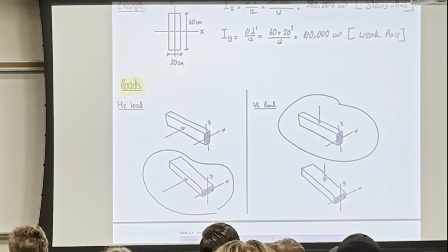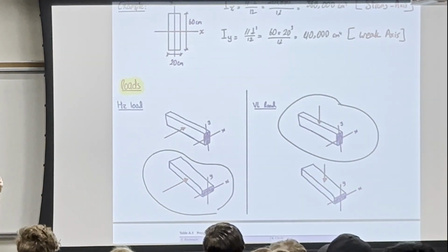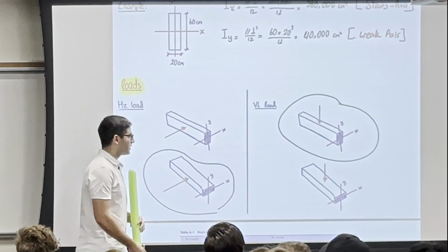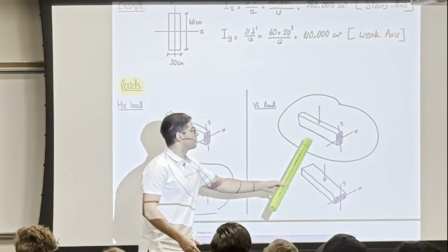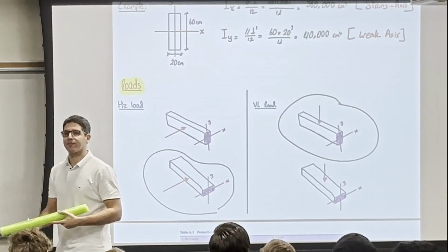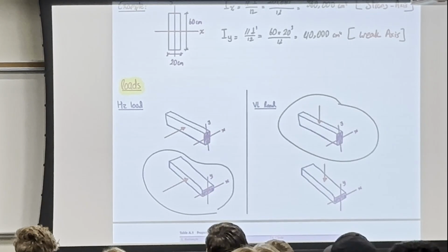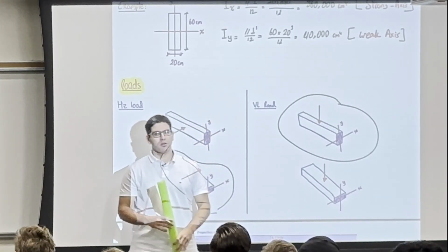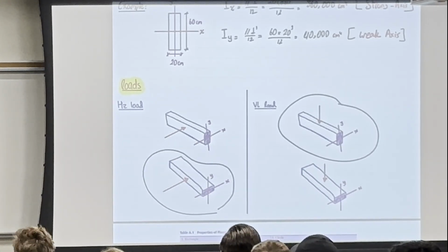Most of your homes are made of wood. Wood is a very weak material in terms of the modulus of elasticity compared to concrete and steel. But engineers know how to align the cross-section to benefit from the stiffness of the shape. So if you know how to align your beam, you get an advantage. It's a weak material, but it's important to know how to align it relative to the load.